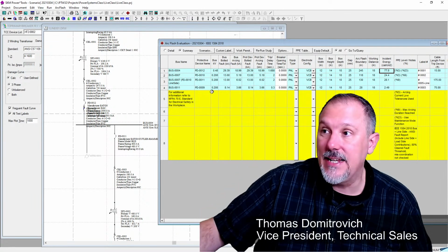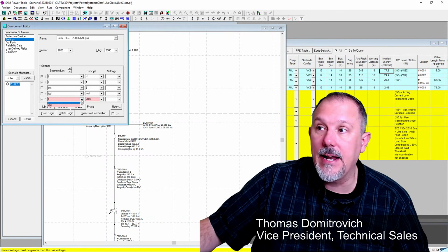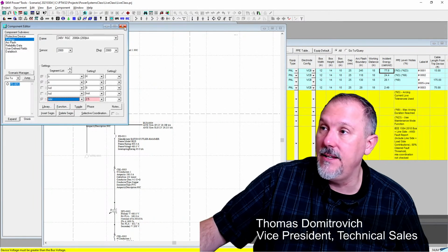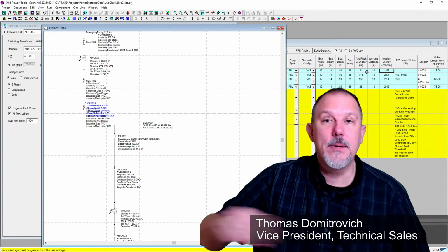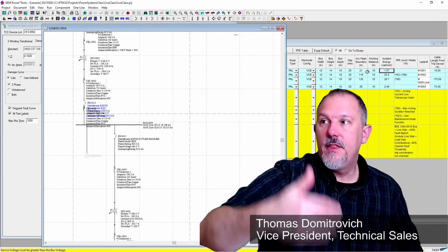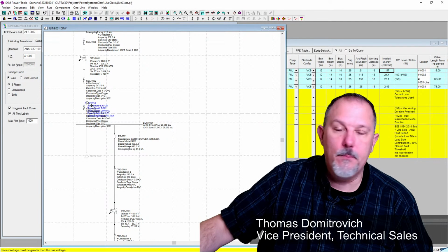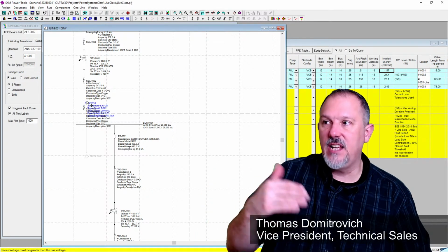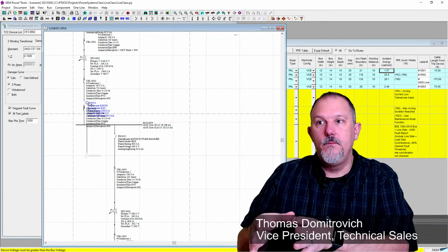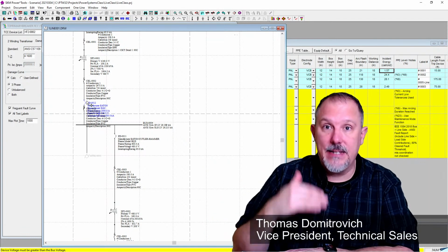And now what I can take advantage of, if I open PD12 and go to settings and put it in maintenance mode at 2.5 times setting, I take my calories down to 1.57 for the electrical worker. That's a safety by design principle. Popping out that secondary main breaker, instead of including it in the enclosure, take it into a separate enclosure, put the arc reduction maintenance switch on it, and I can reduce the incident energy.